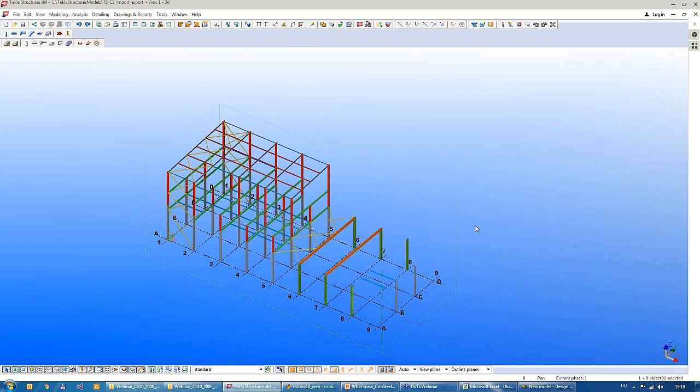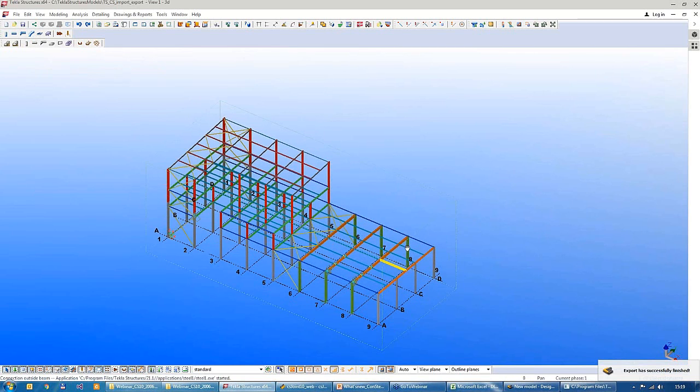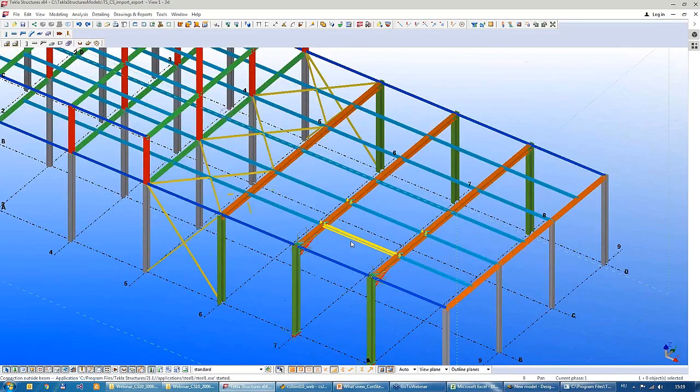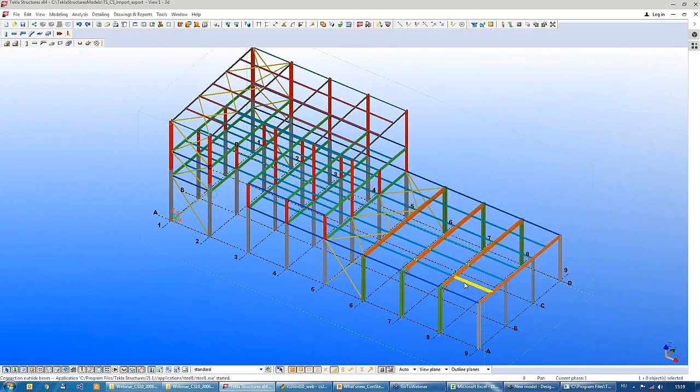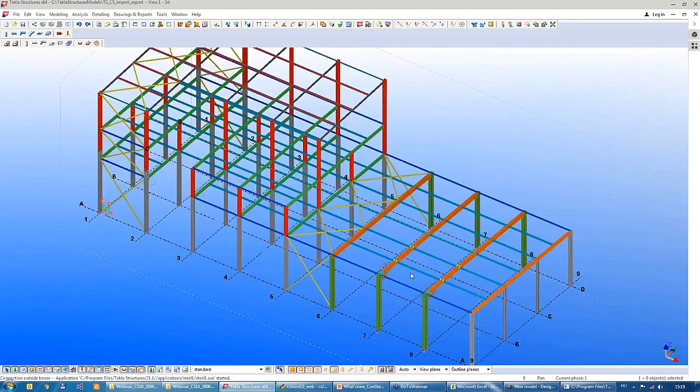And the export process is starting. If you look at the Tekla model, all of the elements were exported back with the proper materials, and all of the placed joints were created with the inbuilt Tekla macros. Now you can see, not just the member parameters, but the class parameters were also exported back to Tekla.